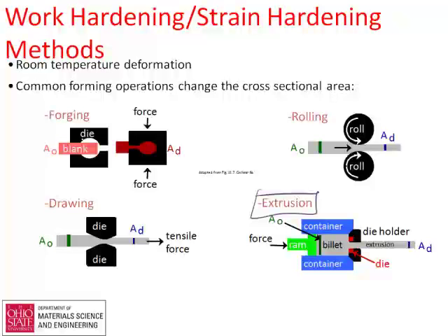So forging is basically you take a piece of metal. This can be done hot or cold. You clamp it between some very hard steel dies. You make a shape that way. Drawing is the way we make wire. There are some great ASM demos of using drawing plates to take wire of one cross section and reduce it to a new cross section. You can see that those wires get stronger and stronger as you put more and more cold work into them.